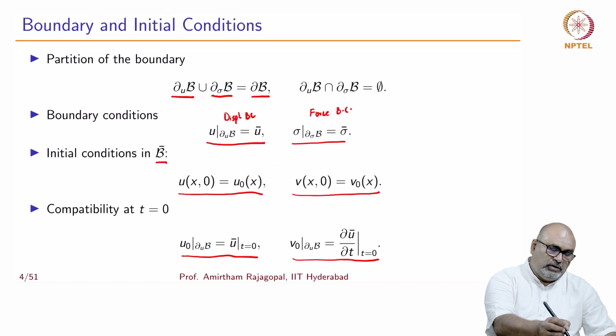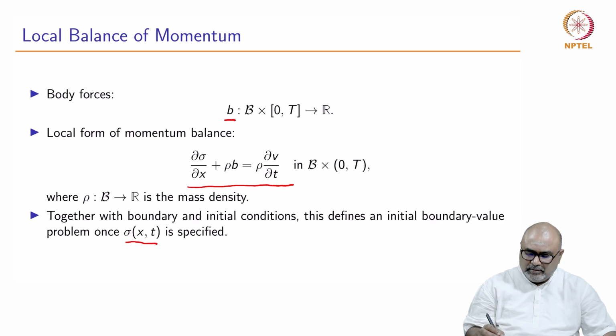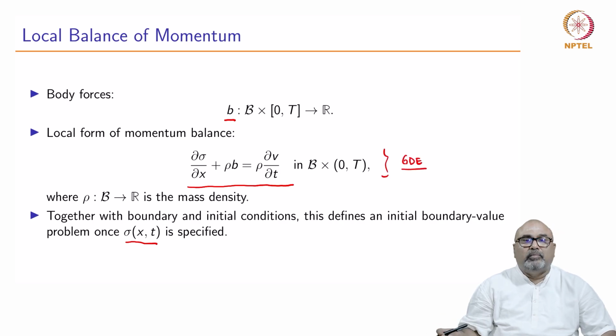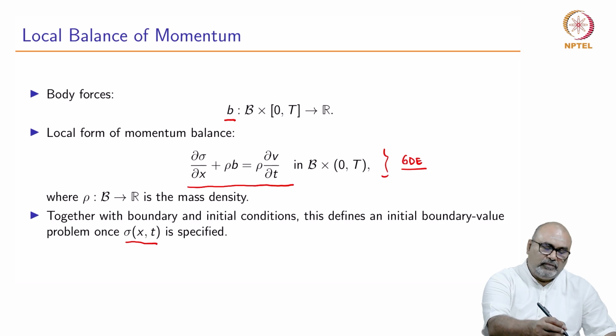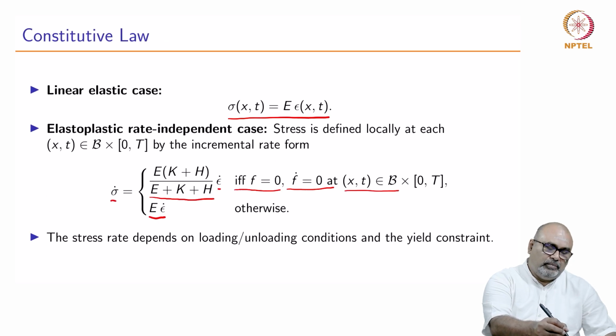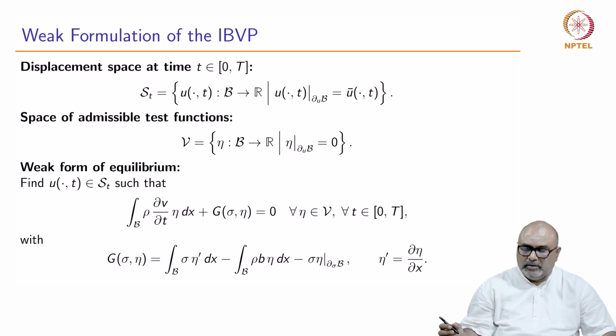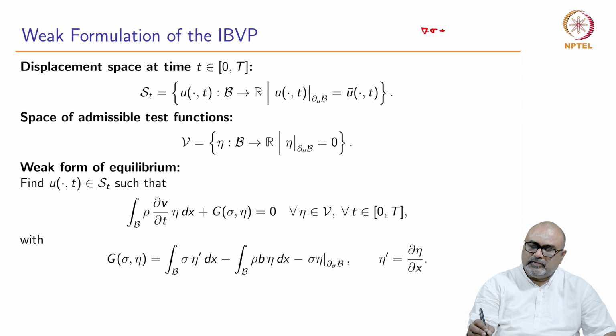So, the original governing equation that we have represents how the domain is behaving under the influence of the external loads and how the body is deforming. This governing differential equation allows us to define, in approximate methods, what is the residual that is coming. The original differential equation is divergence of sigma plus body force is equal to 0.